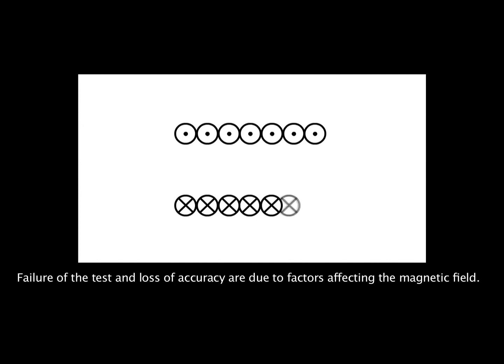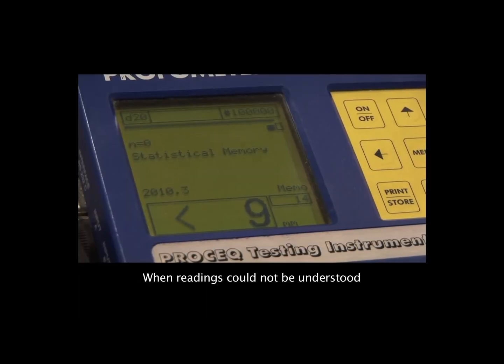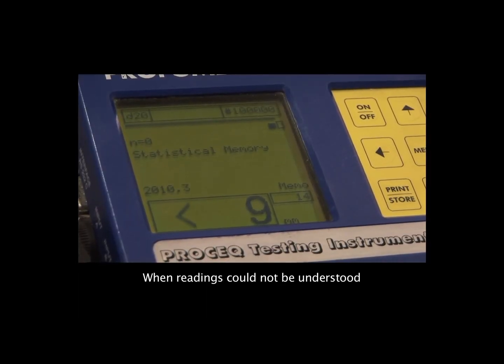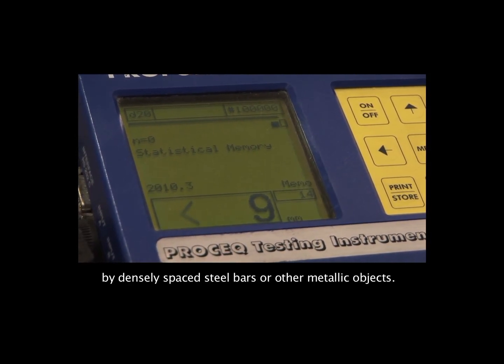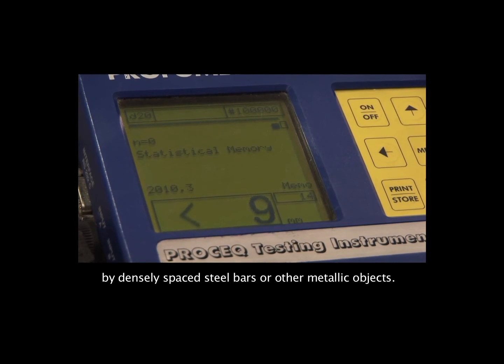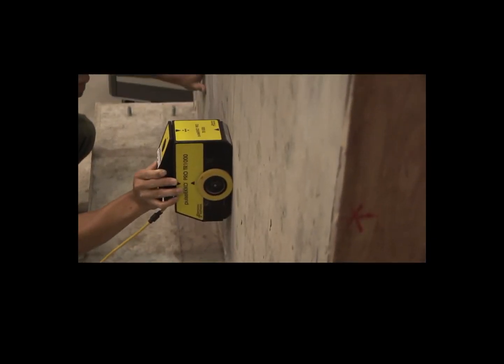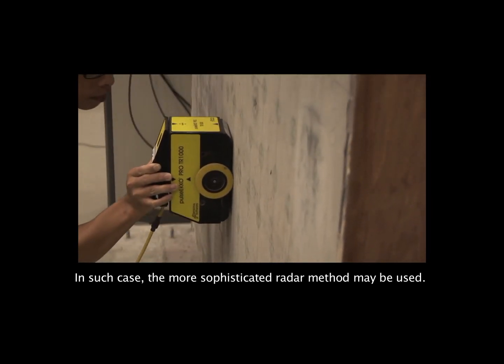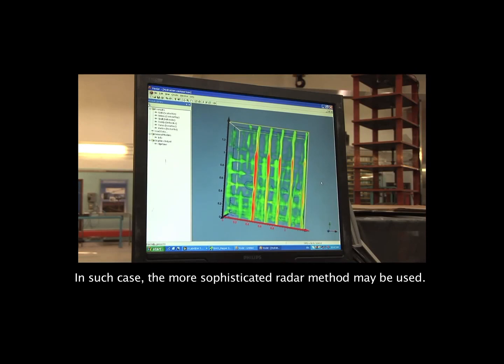Failure of the test and loss of accuracy are due to factors affecting the magnetic field. When readings could not be understood, the signals are possibly interfered by densely spaced steel bars or other metallic objects. In such case, the more sophisticated radar method may be used.